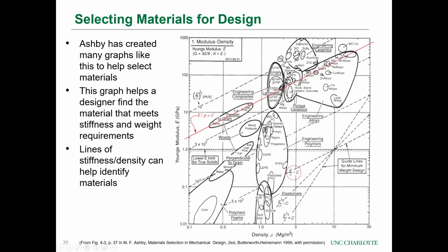Then we get up here, we get into laminates, carbon reinforced laminates, glass reinforced laminates. And then we get into some other materials. We've got magnesium alloys, and we smash right through those. Porous ceramics. And then over here we have all these engineering alloys. This big circle here is the space of engineering alloys. And then we go through titanium alloys, zinc alloys, copper alloys, nickel alloys. Looks like steels, magnesium, tungsten alloys. So we can get this mapping of what is possible.